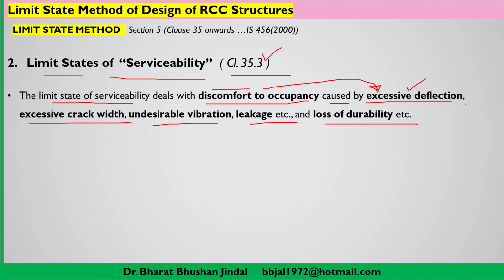So when you are going to design a structure and taking care of the limit state of serviceability, first of all you have to be sure that there should not be excessive deflection, there should not be cracks of greater width, or you will be restricting a particular crack width, and there should not be any type of vibration, leakage, or loss of durability.